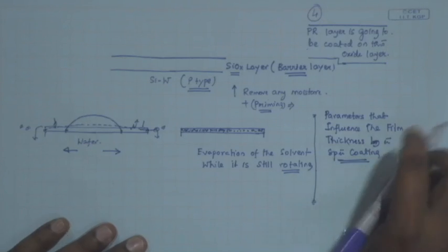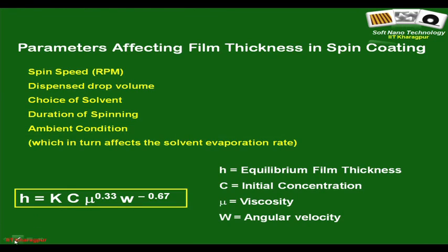So, this is an important issue. There are some relations like this, how thickness varies with this and that. These are mostly extremely empirical data driven relations, and they often consider some sort of a steady uniform rate of evaporation, which you now know is not the case because spin coating actually has different regimes.